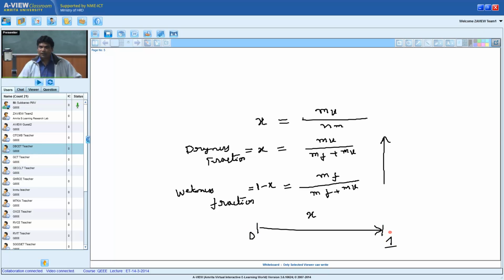And beyond that, there is no meaning of x at all. The definition of x is valid only when you are inside the dome. If you are outside the dome, x has no meaning at all. It is a local definition.